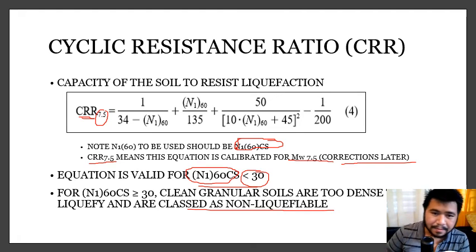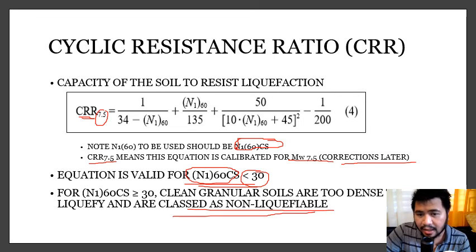Okay? You can't just use raw SPT data and call it a day and say that it is not liquefiable. That's wrong. You will see later in the examples that SPT N values can change a lot once you start applying the corrections. Corrections are very important because corrections give you the real numbers.